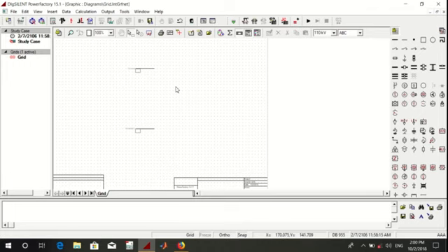Now the two bus bars are defined. I have drawn the bus bars. I have defined the parameters. Now I want a source to feed this bus bar. I can select a synchronous machine also. If you go with the mouse to each icon, it shows the name of each icon, what this icon represents. This is synchronous machine, asynchronous machines, and maybe we can feed from the grid, external grid. I select external grid and I bring it to feed